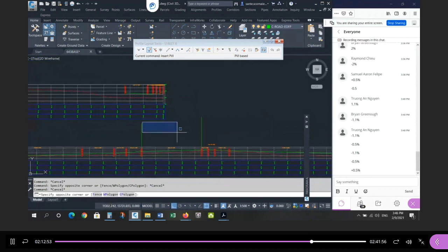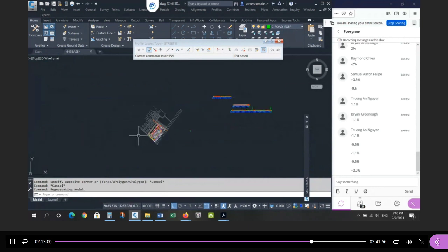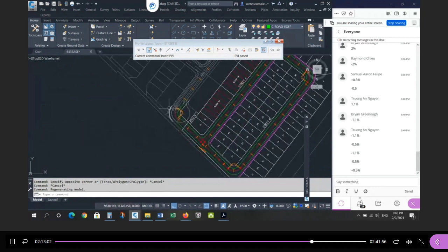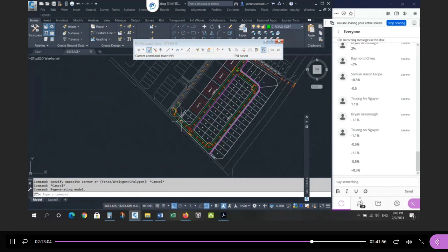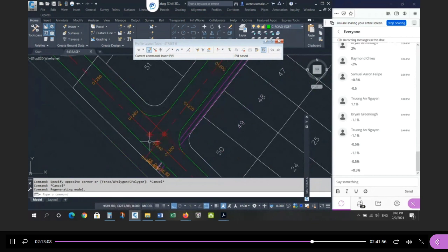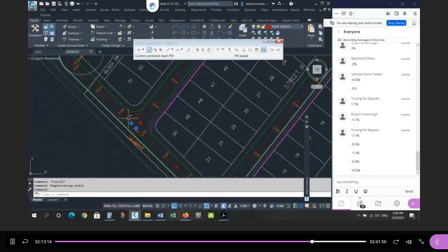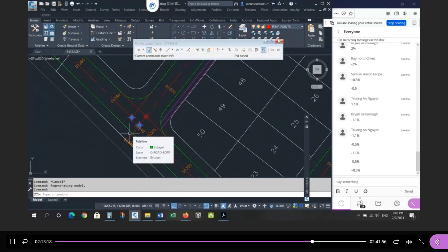And now I need to design between here and here, which in the plan view is from this elbow to this elbow. I need to design between the two elbows, keeping in mind I have this intersection. So in the intersection, I want to know where this low point is, and I want to know where this intersection point is. So I'm going to project these 2 points to the profile because they're key stations.